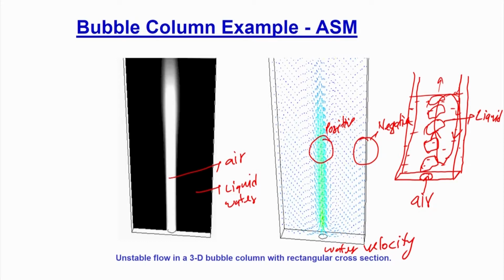So, that is the advantage, but the major problem is, as I said, that the particle relaxation time multiplied by F drag should be less than 0.001 or 0.01 depending upon which group you follow. I would recommend 0.001 here. And second, the flow should not be countercurrent and the discrete phase fraction should be less than 10% for sure. So, the lower the discrete phase fraction, the better the accuracy. The model has been developed to be relatively simple, as we see in the equations, and you can solve it with this approach. So, that is all about the algebraic slip model. Some people also call it a mixture model.